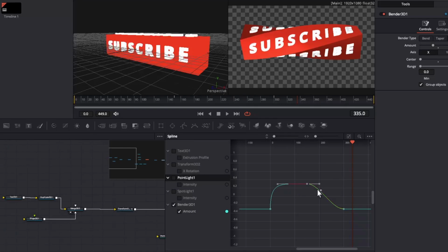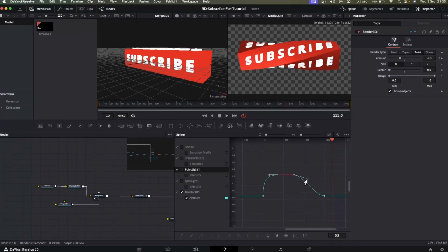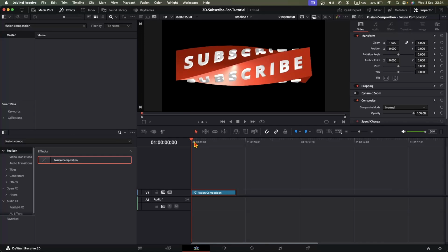And then here, if you hold the Option key or the Alt key, you can just change the right part of the spline. Bring it up here. Now select this point here and let's make a spline that looks something like this. And this is the final thing we had to change. Now we have the full 3D subscribe animation with lights, bending and transformation in DaVinci Resolve.